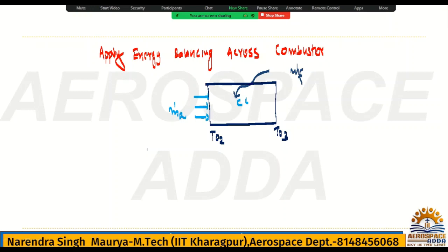I'm asking, what is the work of the combustion chamber? To convert chemical energy into thermal energy. So what will be the chemical energy? The chemical energy will be the chemical heat value, which depends on the fuel heat value. m dot f into heat value will be the chemical energy, and if you multiply by the combustion chamber efficiency, the effective heat energy will be how much portion of the supplied chemical energy is converted into thermal energy. It depends on the combustion chamber efficiency, eta cc.